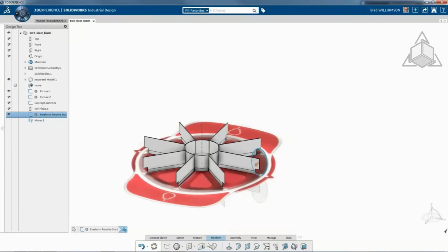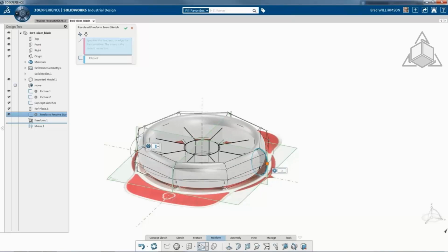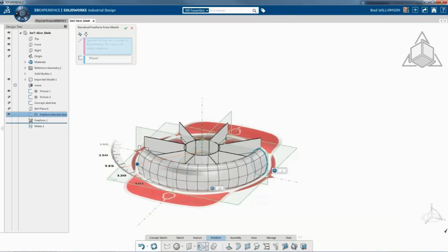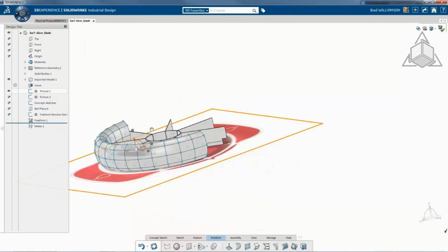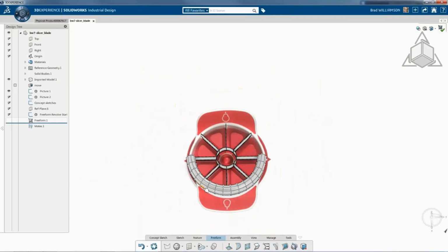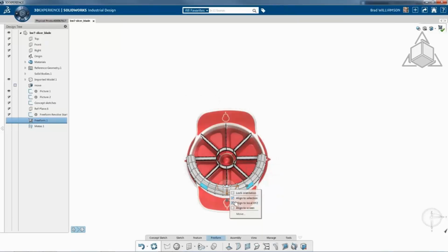So let's take a look here at our blades. We've got some more sketches in there to give a little more shape. But what we're going to do is start from what we call a primitive, a free-form shape where we control the number of segments. And I'm only going to have this at 180 degrees. All of these segments, or something we call cage points, can be used for push-pull drag of subdivisional modeling. As we orient this, I'm able to select a couple faces that are segmented in a location and use something we call the robot.